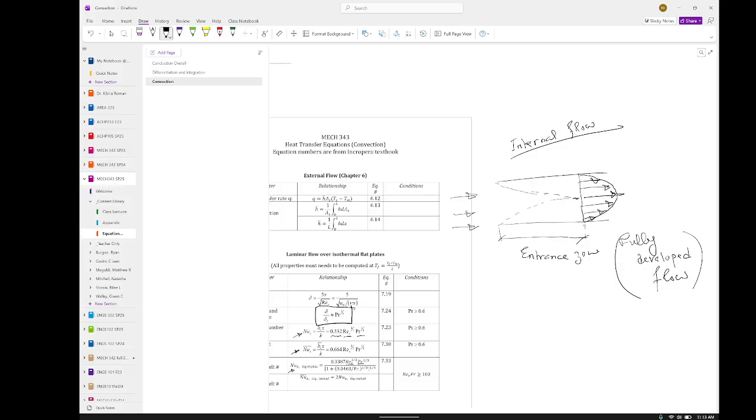And the other distinction I established before is this entrance zone effect. You see that? The conical shape, the core stream that I drew, there's the entrance zone effect. In the core stream section, what is happening actually? Let me draw the free stream velocity. You see, this velocity, this long line is the same here. But here in this zone, what is happening? You have this velocity boundary layer like this, right?